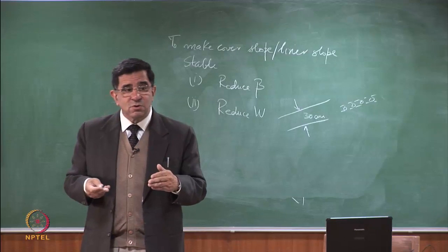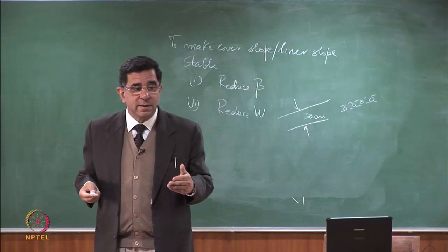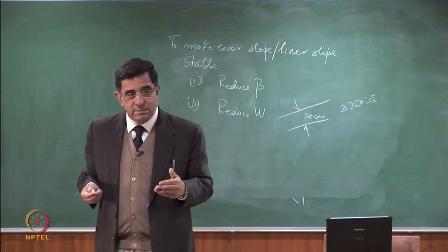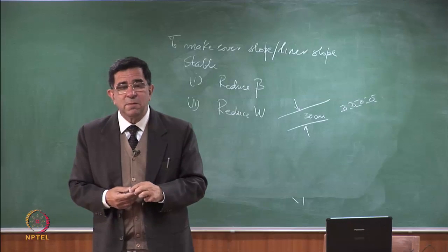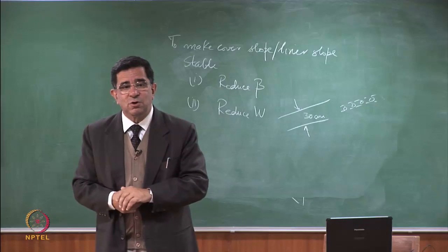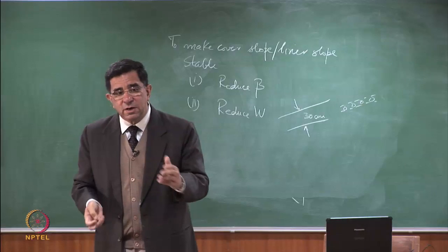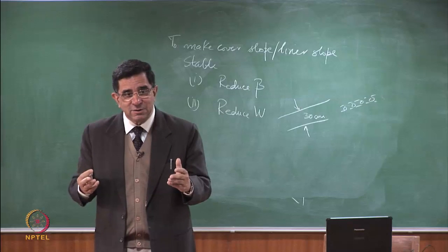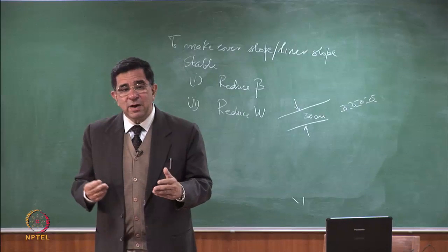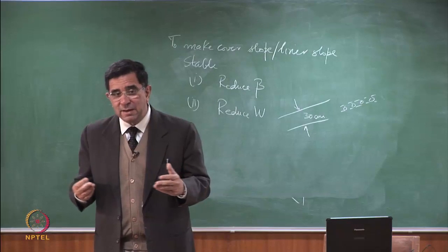Instead, if I was to use a geocomposite, what would it weigh? Much lighter. What is the grams per square meter of the geotextile? I told you that you should adopt a geotextile of 400 GSM. 2 geotextiles, 400 plus 400, 800 GSM. Add the weight of the geonet to it, another 800.